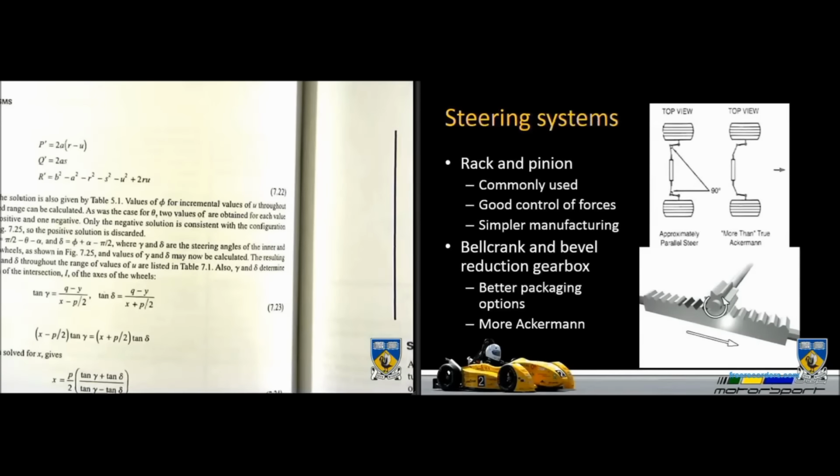So you can see the position of that from the box on the top there, and the distance from the centre of the wheels actually changes your Ackerman ratio, and changes all the different system values. So your moment arm, your torque arm out on the upright of the wheel itself, actually changes where you want to position that to achieve 100%. Then you can simply move that forward and back, maintaining the same geometry, and get positive and negative Ackerman. Downside of that is you're quite limited in how much you can adjust that.